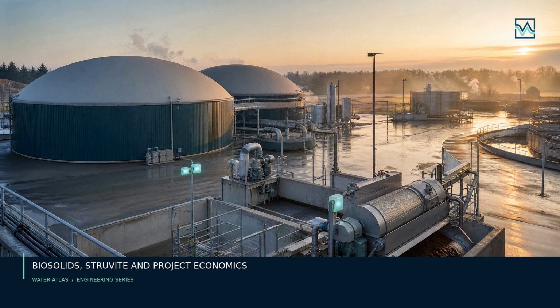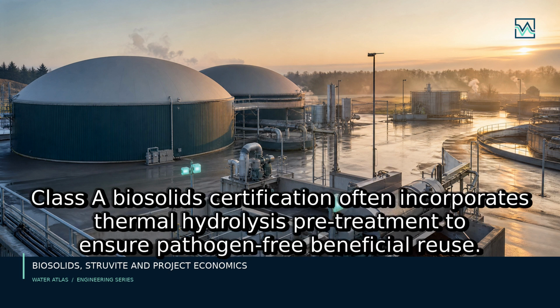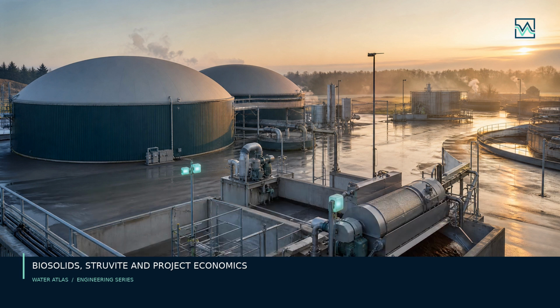Smaller facilities may find conventional mesophilic digestion economically prohibitive unless integrated into regional centralized hubs or paired with food waste co-digestion to boost gas yields. Conversely, large metropolitan water resource recovery facilities can readily justify advanced thermal hydrolysis and gas upgrading infrastructure. Careful risk assessment, pilot testing, and lifecycle cost modeling are indispensable for ensuring that resource recovery projects deliver sustainable financial and environmental returns. The transformation of wastewater treatment plants into active water resource recovery facilities represents one of the greatest engineering achievements of our era.